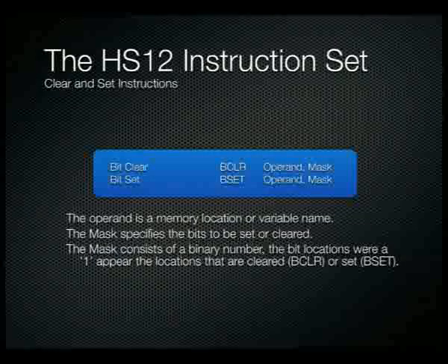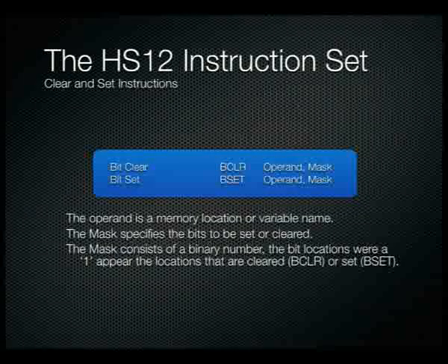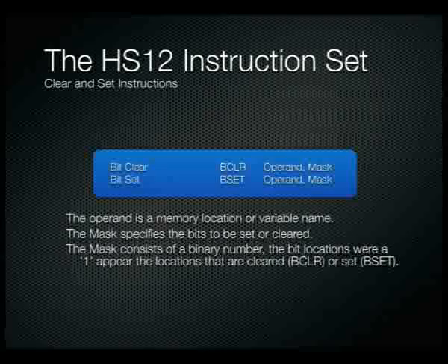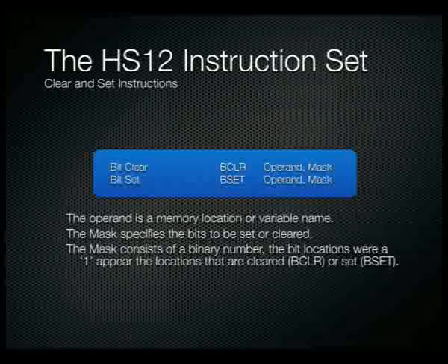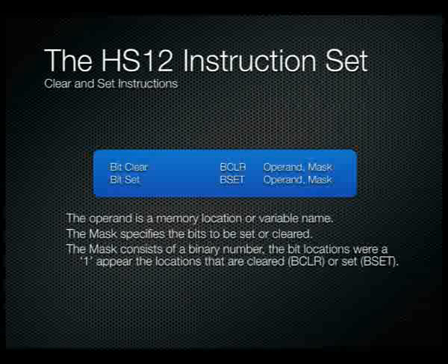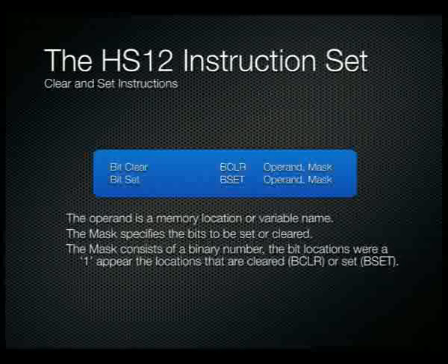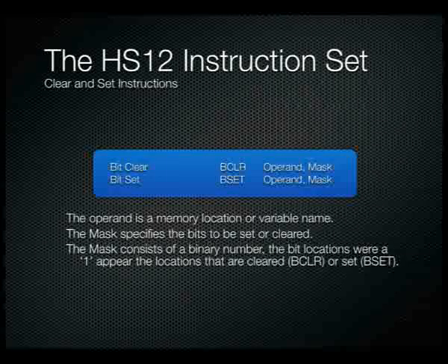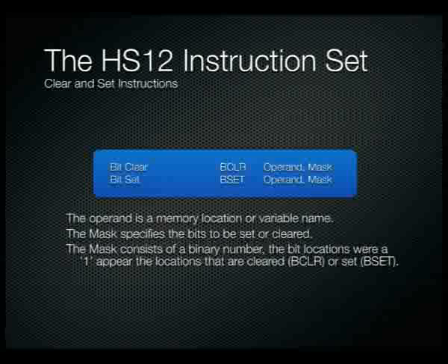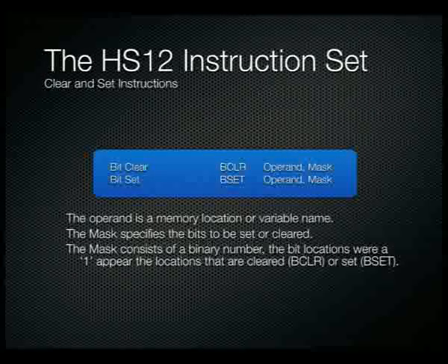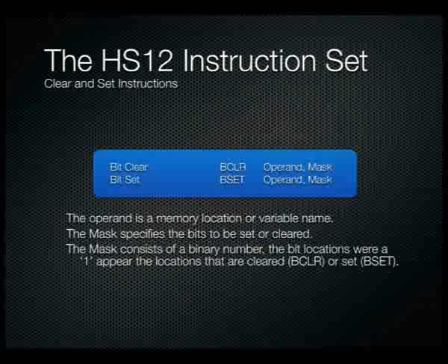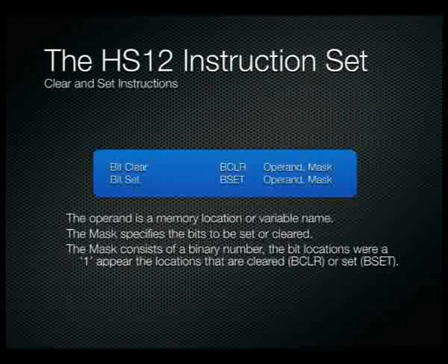As I said before, we have the ability to set or clear particular bit values inside a register. This is very useful when we're dealing with subsystems where particular bits control particular aspects of that subsystem. We may need to set just one particular bit but leave every other bit alone. We might want to change only one bit value but not affect the other bits, leaving them untouched. So we actually have bit set and bit clear commands.